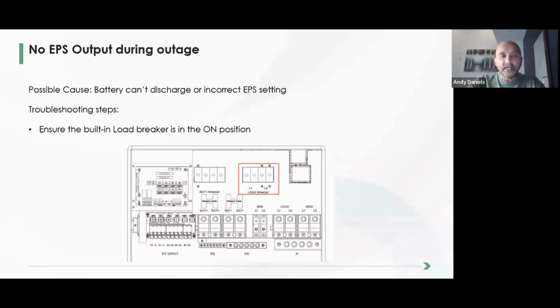If you've chosen lithium as your battery type, then you have to nominate the correct battery brand, and also make sure that the communication cable between the master battery and the inverter is the correct cable. Our machines run on battery communication via the CAN bus protocol. So our pinouts are pin 4 and 5 for CAN high and CAN low.